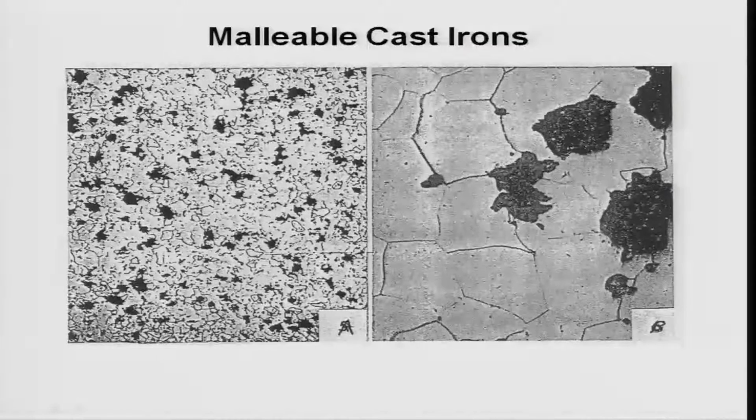So, you have basically what is called tempered graphite, or solid state formed graphite, and then the surrounding is a ferritic matrix. As you see in a higher magnification picture of the graphite, you see irregular, separate graphite, correct? Here also. Because of this tempered graphite, malleable iron is very malleable. Malleable means what? Very ductile.